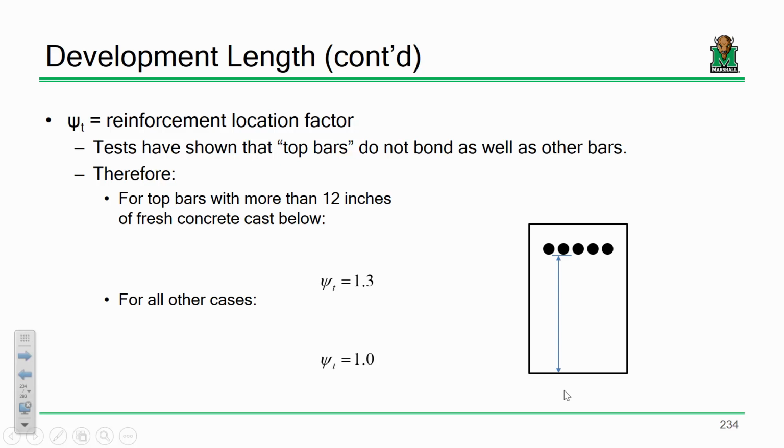How many of you have had 321, have had materials lab? Or how many of you have ever cast a concrete cylinder or done any concrete work in the backyard? Okay, so you're casting a cylinder, right? Tell me how you fill the cylinder up. What do you do? Somebody tell me. You tamp it, right? And then you fill some more. And there we go. Why do you do that? Air voids. That's it.